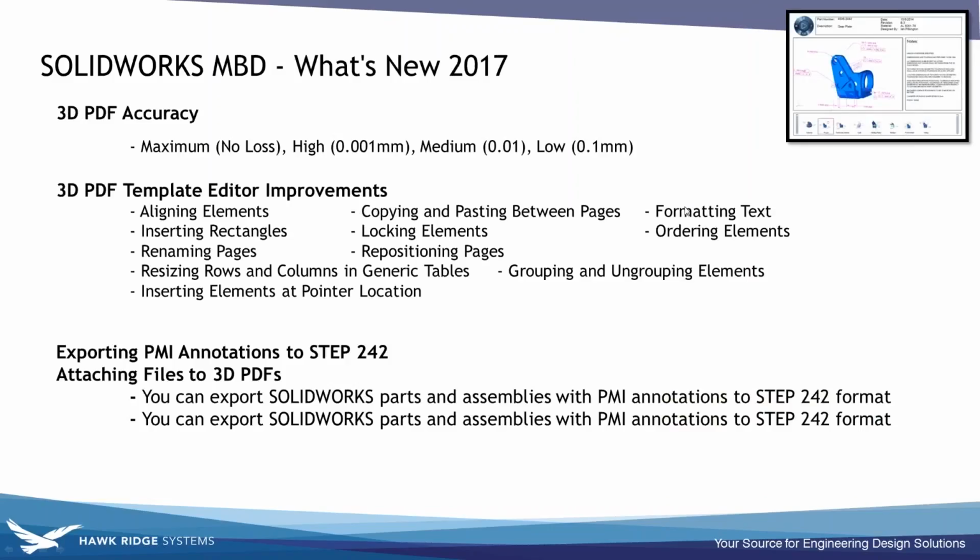Okay, so let's go ahead to the next item on our agenda, and that is SolidWorks model-based definitions. This is one of our newest products. If you're unfamiliar with what this is, SolidWorks model-based definitions is to be able to add PMI data to the 3D model. That's going to be dimensions, annotations, notes, bill of materials, all within the 3D view, and then save that out as a 3D PDF. So it's a way to go drawingless. It's also a way to go paperless. And those dimensions are all driven by DimXpert.